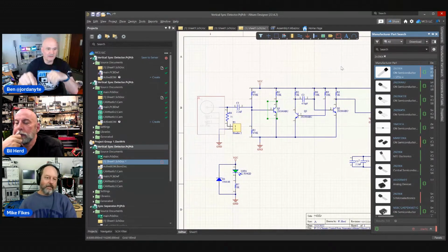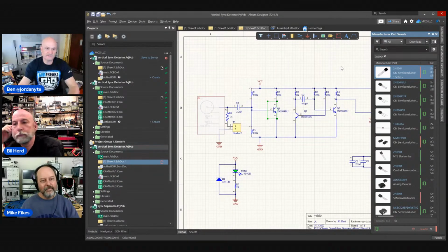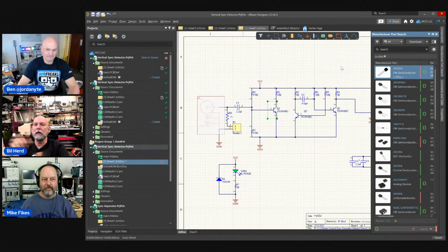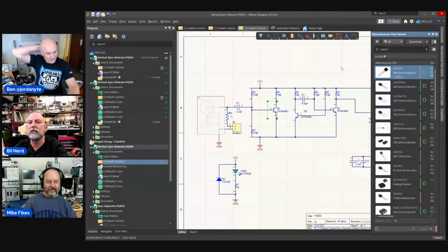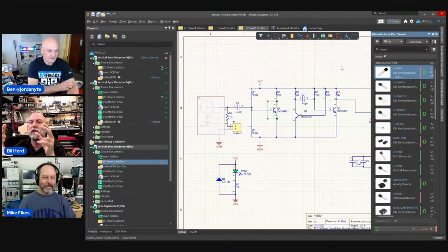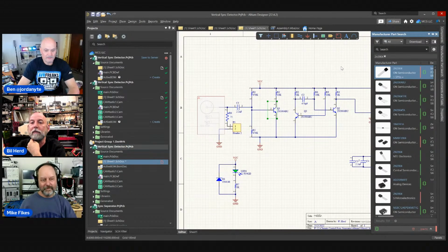All right. But the problem here, and the other reason people don't want to use Altium or Eagle with the built-in NG Spice engine for simulation, is it doesn't support encrypted models. Tell us about encrypted models and black boxes. Encrypted models is why TI has a free version of PSpice for download that you can request. It's what it sounds like. It acts like a black box with just pins without giving away how they did it, right? Exactly. It'll behave accurately according to the behavioral silicon model. Yeah, it's according to the silicon.